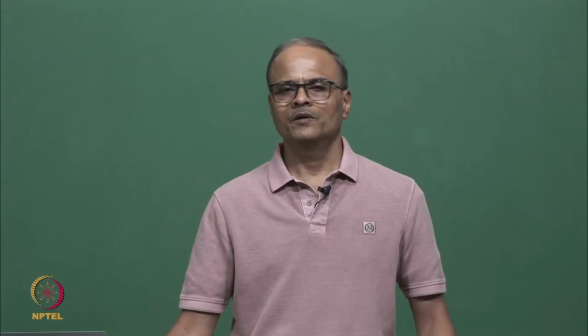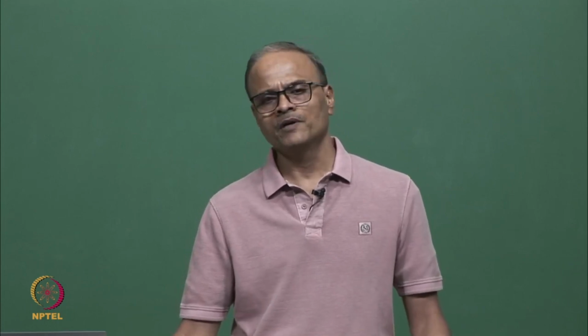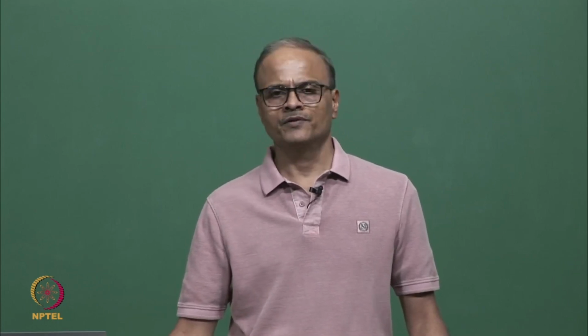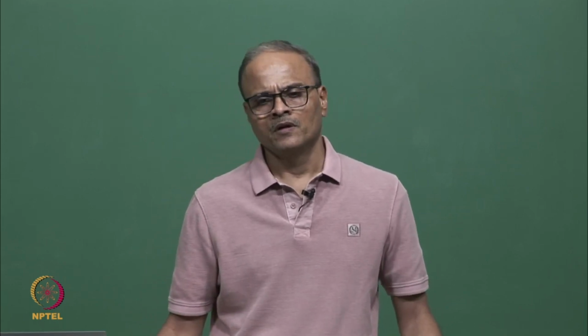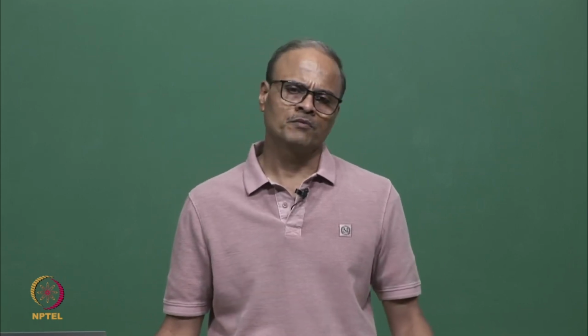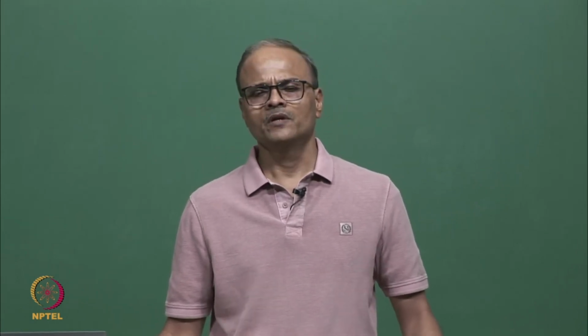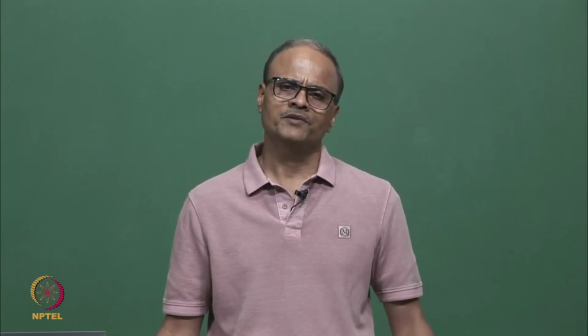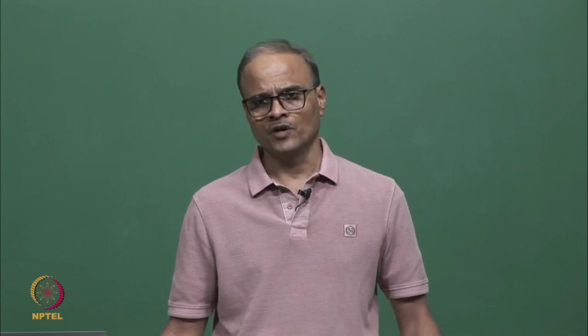Hello everyone, welcome to this lecture. In the previous lectures, we have looked at how the structure can be excited using impact hammer and how the force can be measured. We also looked at how the resulting response can be measured. So once the force and response signals have been measured, then we need to find a frequency response function. So in the lecture today, we are going to look at some estimates of frequency response functions, and also we are going to look at what is coherence function.